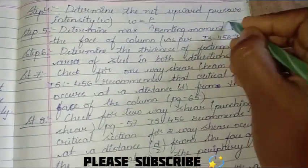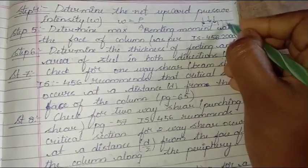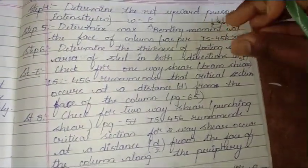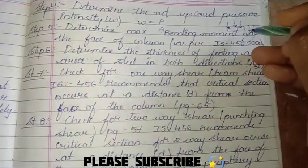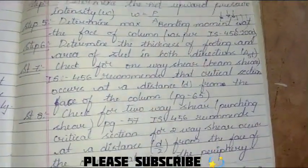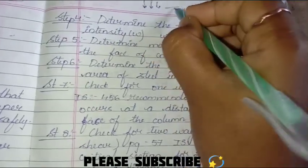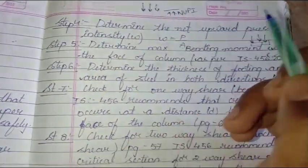Whenever we are talking about the load that is applied downwards, we know some forces would be there that would be lifting it upwards. So whenever we are designing the footing, we should also consider the upward pressure that is coming. Here we are designing it for the downward load, but we should also consider the net upward intensity, whatever the tendency of the soil to uplift the footing is. So we are considering not only the dead load acting downwards, but also the net upward pressure intensity applied from the soil to the footing.